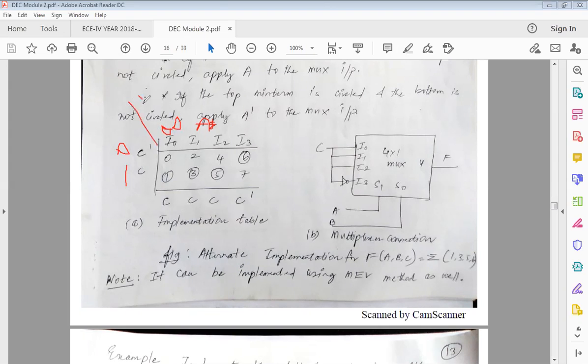In your K-map, you were taking A, B this side and C here. Now you're able to understand. So AB is taken here, the last bit will be on the left-hand side, and the first two bits on the right-hand side. Here is a small twist. Instead of taking A towards your left-hand side, I'm taking C here. So if I say take C as your input, this is going to be your small change in the question. You understood, right?